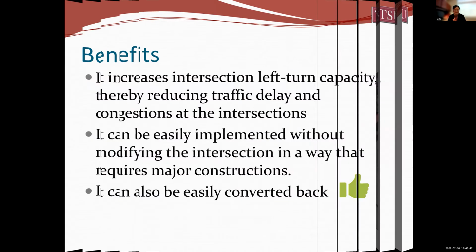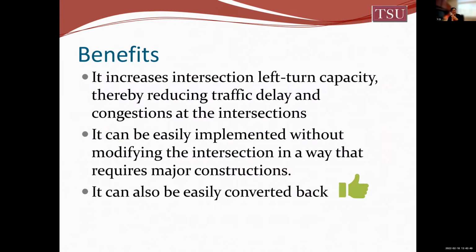Why are we interested in this particular design? First, as I mentioned, it will increase left turn capacity because you doubled and tripled the left turn lanes. This is a big benefit. I like the idea that it's using the existing facility. You don't need to build any new lane, but you increase the capacity.